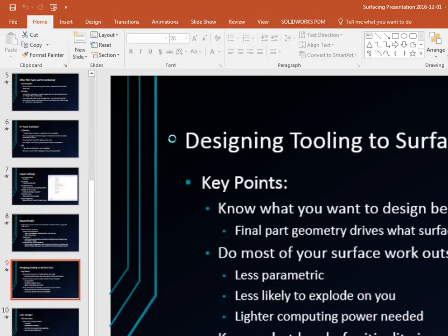So I'm going to fillet all of these edges, and some of these were harder to fillet than others. You can see this one here has a variable fillet instead of a normal fillet, because if I start the fillet tool, you can see it doesn't want to make this jump here. It doesn't like it even if I pick multiple edges. One thing that we found is that variable radius fillet does a good job where other fillets can't solve.